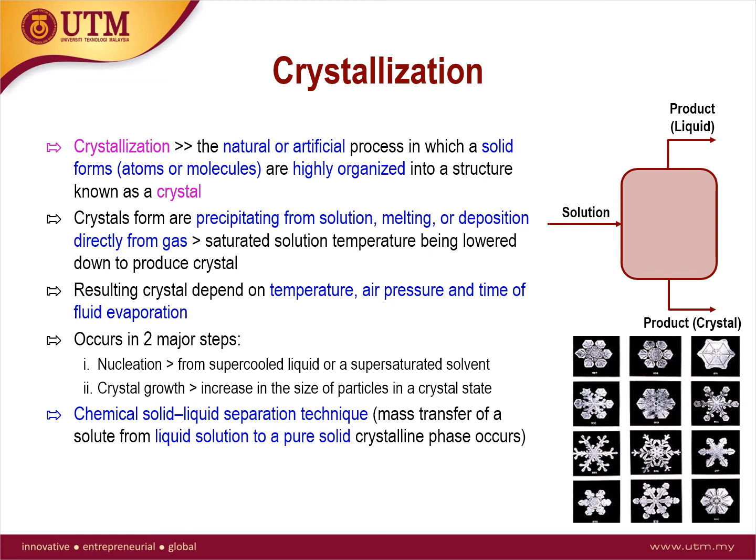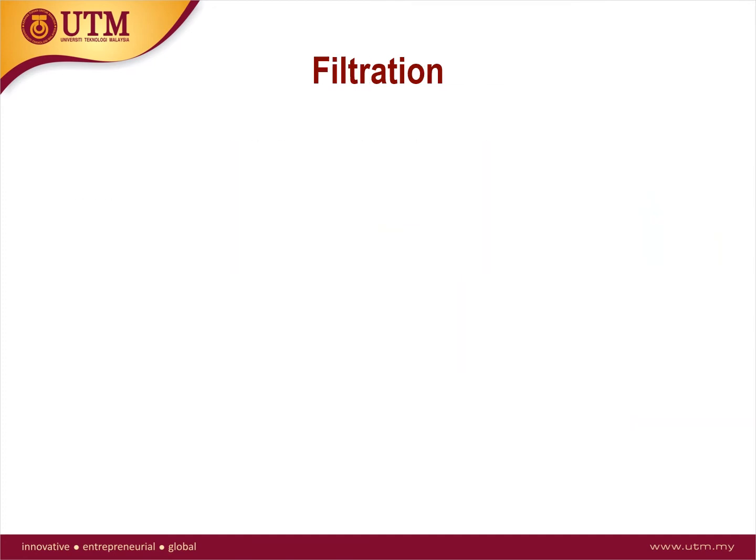Crystallization is also a chemical solid-liquid separation technique in which the mass transfer of a solute from the liquid solution to a pure solid crystalline phase occurs. In chemical engineering, crystallization occurs in a crystallizer. Crystallization is therefore related to precipitation, although the result is not amorphous or disordered but a crystal. An application of the crystallization process is a snowflake during the winter.